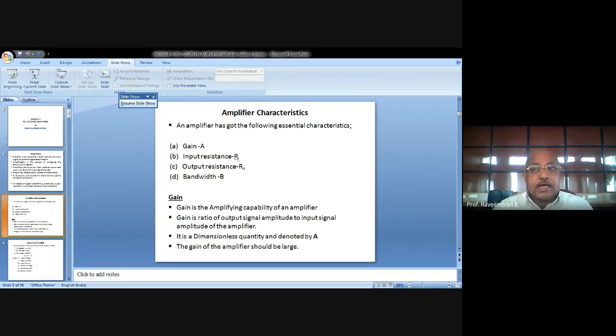If you give the input signal to the amplifier and it is attenuated, you are getting a reduced signal at the output. Amplification means the amplified version of the input signal, right? So if the gain is less than 1 and the dB gain is negative, then it is an attenuation and we get a reduced signal. That is the opposite of amplification.